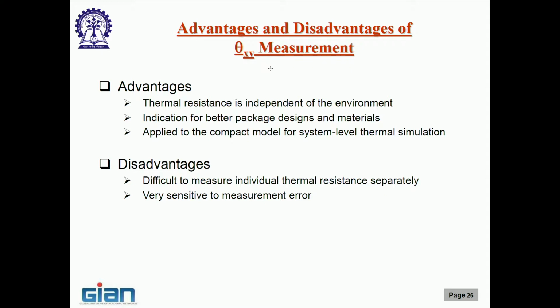Disadvantages is, how do you determine these thermal resistances? Okay. So, one is through just calculations of L over kA, there are correlations for spreading resistance, contact resistance and so on, we can do that. The other is through measurements, and in industry typically the calculations are going to give you an estimate, but if you have to certify a product you have to actually measure, and these measurements are not easy.